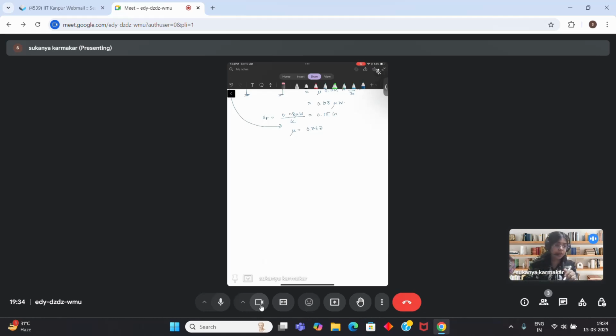So what we are doing here is the dynamic hysteresis plot. The structure is remaining elastic because of the nature of the force. The body is dissipating energy, and you are just plotting the energy dissipated. That is, if you are thinking about a viscous damper, what is the force in the damper? The force in the viscous damper is equal to C into D dot.